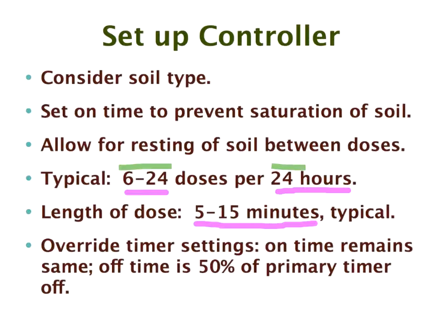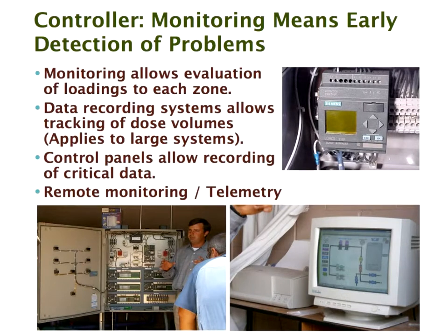So anyway, I leave it to the regulators to decide whether they will allow them or not. As I said, some states or counties don't allow them. Most do. Most systems that go in have the four floats. And generally, if people come to us, we will recommend the 4-float system, and the controller set up to do that.